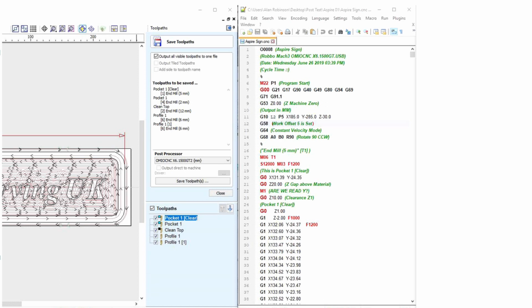To access any of the 254 work offsets, 1 to 254, program G59 P where the P word gives the required offset number. Thus G59 P5 is identical in effect to G58. It is an error if one of these G codes is used while cutter radius compensation is on.